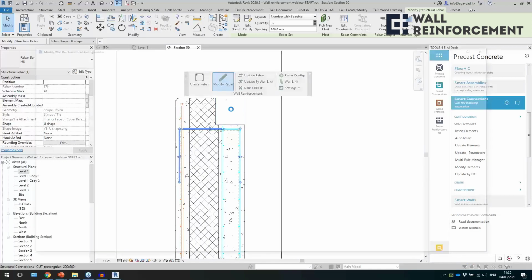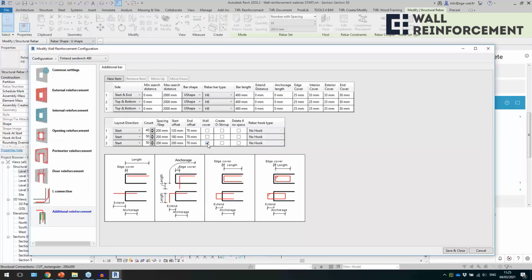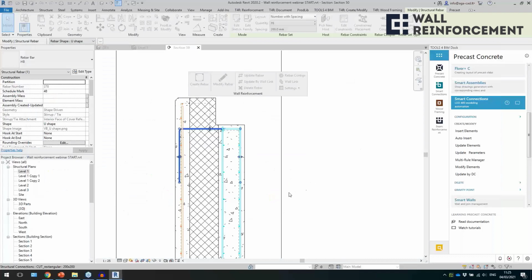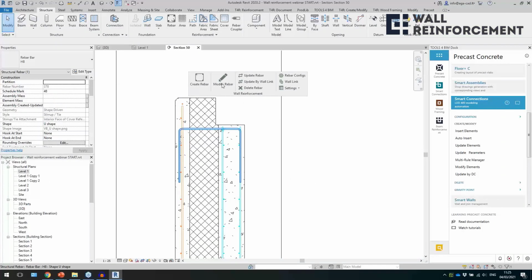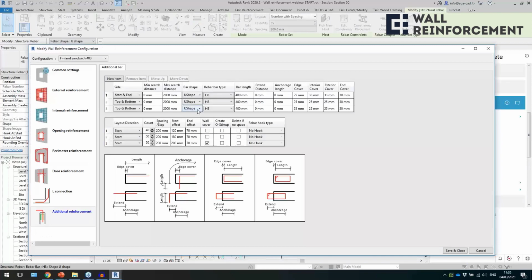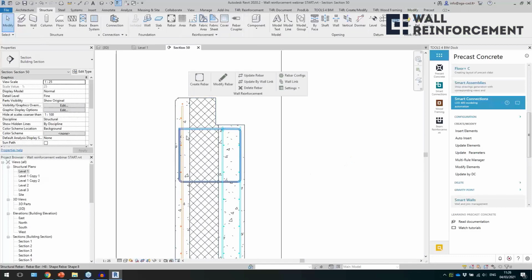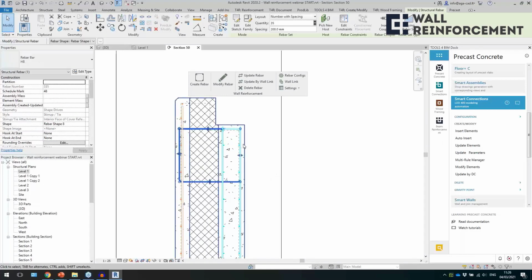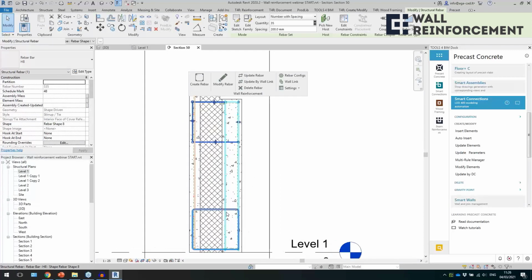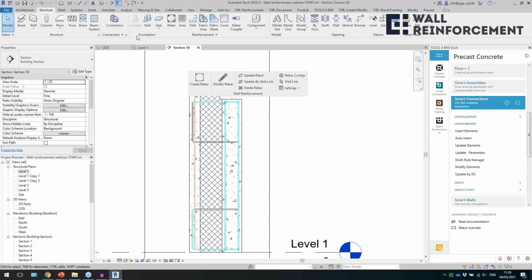How does that happen? We have an option like this, where the cover will not be to the layer of a wall, but it will be to the wall sides, to the full width of a wall. So I can use that for O-bars or for U-bars, right? For example, I will say that this one should be an O-bar. So let's save it. It could be like this, right? I just define what the hooks should be and so on, but then I have these over here.